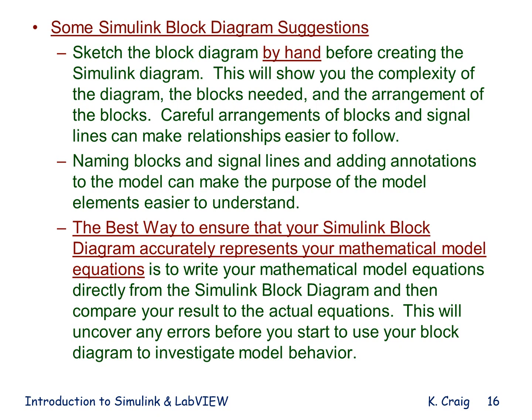If you try to create a Simulink diagram from scratch in Simulink for anything but the most simple systems, the diagram will look very cluttered or confusing, will not be organized, and the time you spend with a hand diagram will give you an idea of the blocks you need, the location of the blocks in the diagram, the location of annotations you might want to include, and so forth.